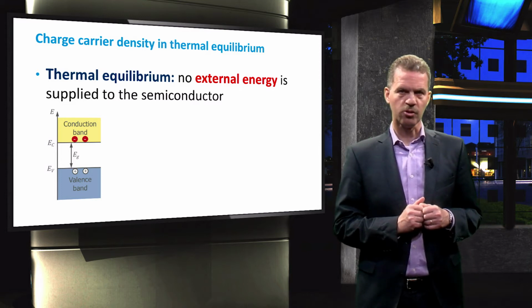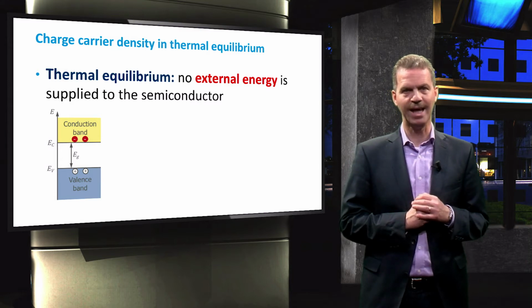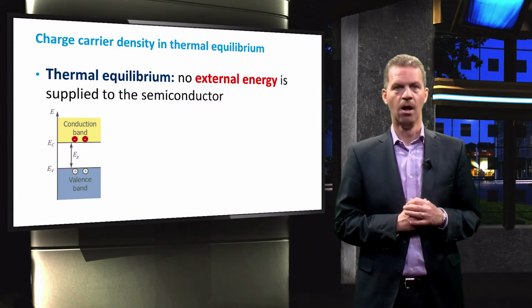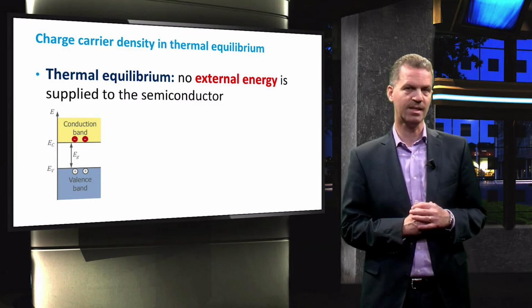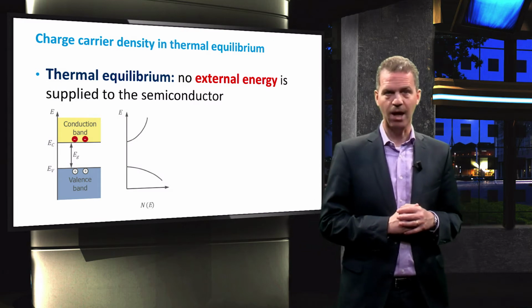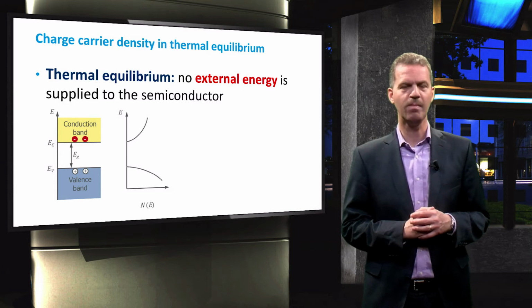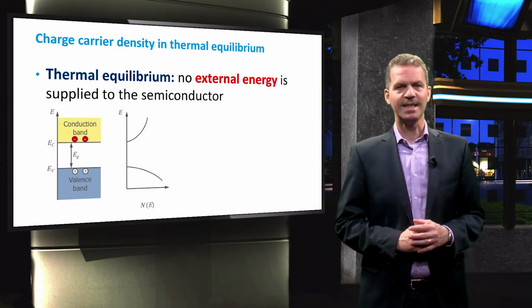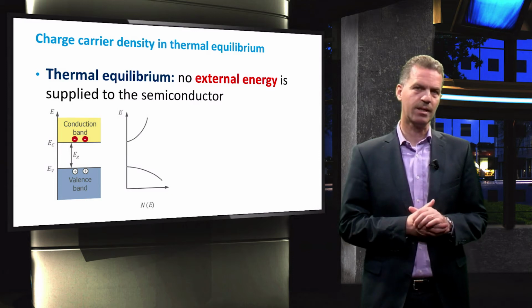According to standard solid-state physics, the density of states, given by a capital N as a function of E, of each band varies with the square root of the energy as displayed in the second graph. What we see here is how the density of energy states increases when moving away from the band edges. These states are allowed energy states that may be occupied by an electron.